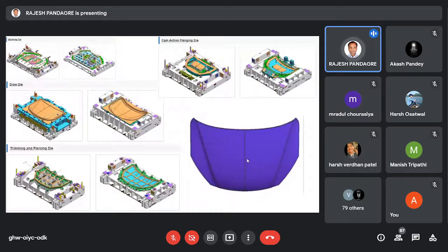So the styling is the most important thing. No product designer and no manufacturing engineer is going to play with that styling. A product developer or a manufacturing engineer will develop the B side only. What is B side? If this hood, whatever you see, is class A, then whatever is behind this hood, which you are not able to see, is B side.